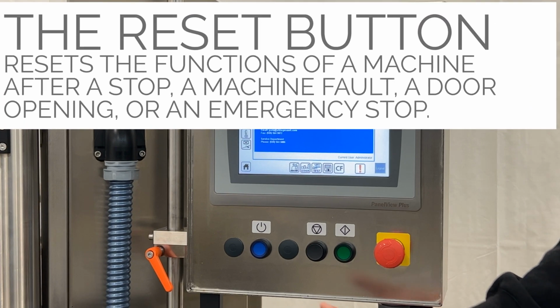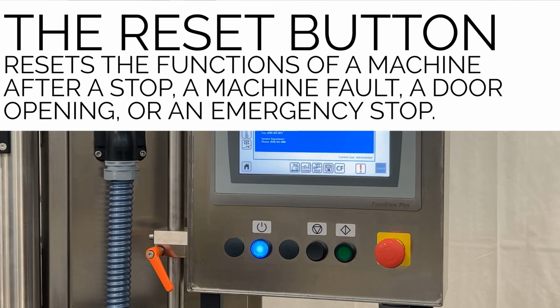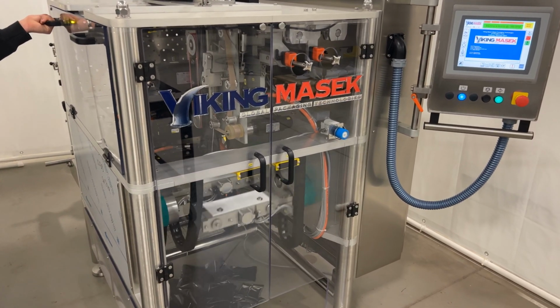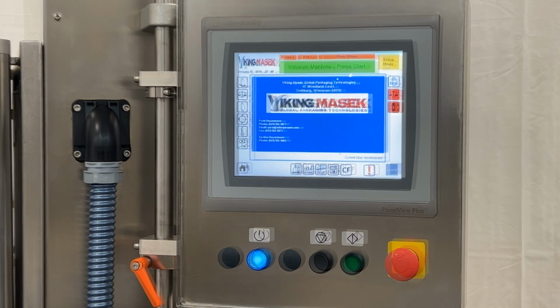Reset. The reset button resets the functions of the machine after a stop, a machine fault, a door opening, or an emergency stop. Once resolving the reason for the stop, press this button to reset the machine. If the machine stopped due to a fault, resolve the reason for the fault, then press reset to clear the fault.